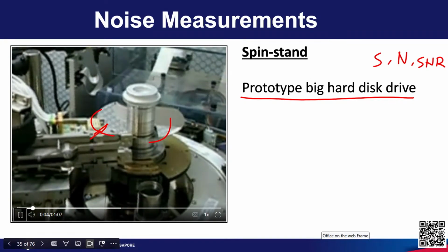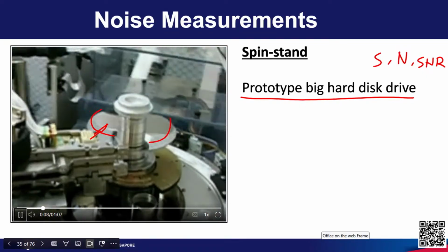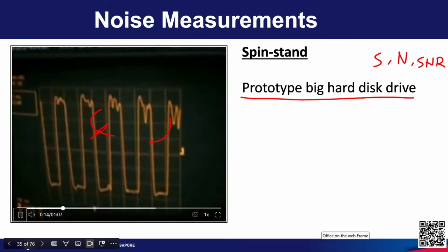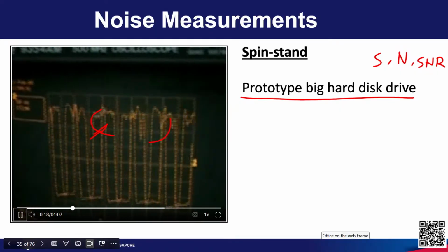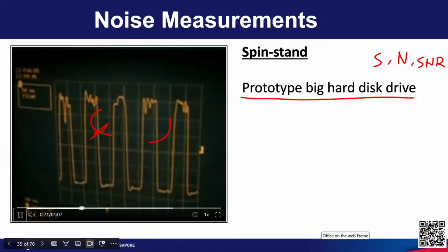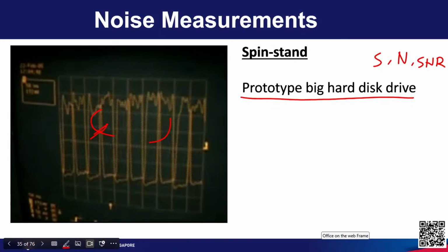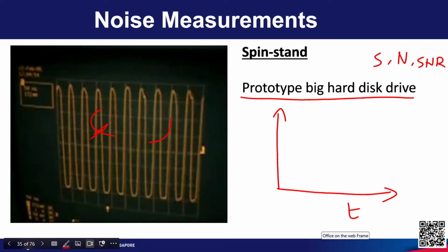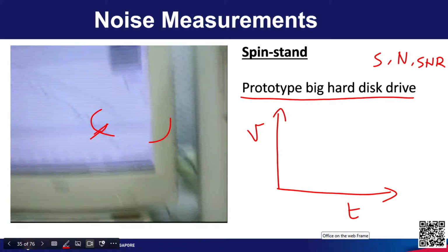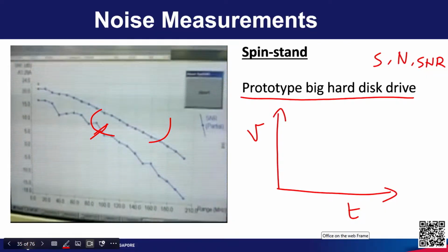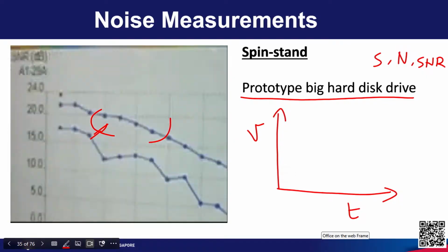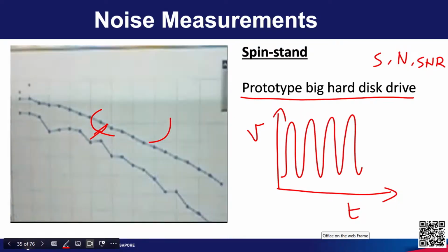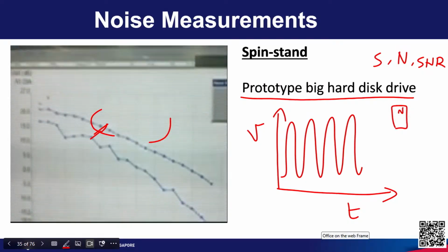Now, the disk is rotating and the head is reading, writing information. So, you can see the plot of measured data. On one side, the x axis is time, in the y axis you have the voltage. The sensor converts the magnetic flux into voltage, and that is what you saw. So, the pulses like this. This is coming from a perpendicular recording disc, where the magnets are like north south.